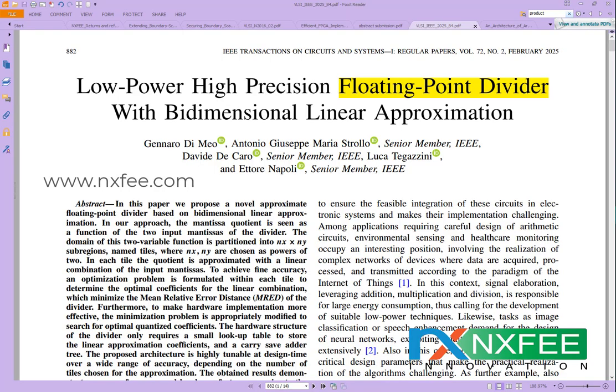Further improvement is achieved by developing optimized XOR mux based full adders and subtractors, which significantly minimize the area and power consumption. So compared to the conventional arithmetic unit, the novelty of this design lies in replacing complex multiplications with lightweight logic structures while maintaining acceptable accuracy, thus achieving an effective trade-off between performance and resource utilization. The proposed divider is described and verified in Verilog HDL, synthesized and evaluated in terms of area, power and delay metrics.